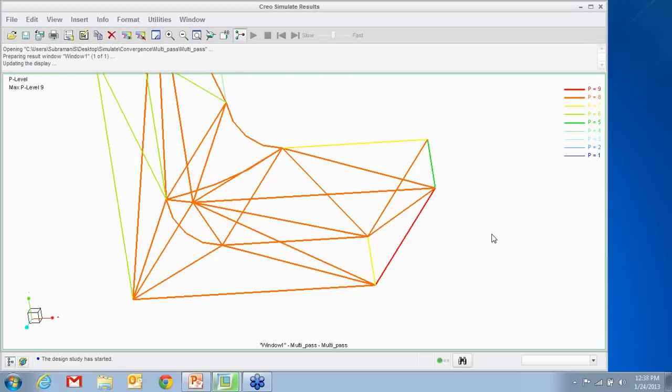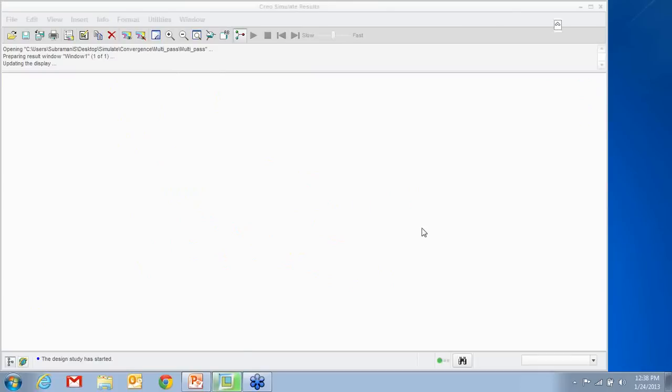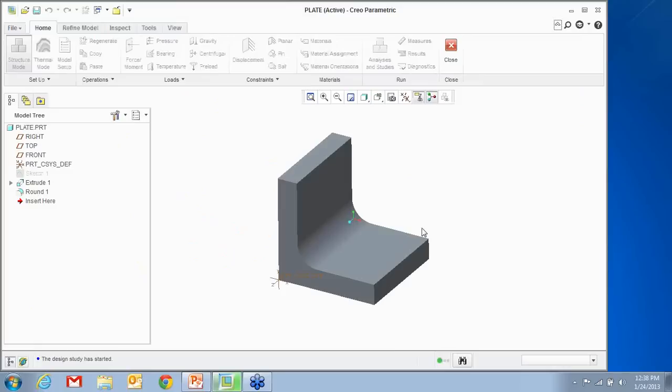So in that way, you don't really have to make the mesh very, very small to get a more detailed localized result. If you increase the plotting grid from 4 to say 6, what you're doing is calculating the answer at the end, and 6 different locations along the element edge, and it does that for each of the edges. A good value to have is the default value, which is 4. You can choose to go up to like about 7, which is a decent number if it's a very, very critical part.